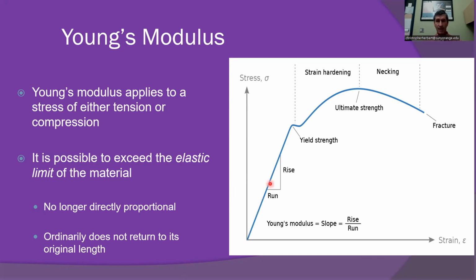But once we go past some point, in this case, we're seeing something called the yield strength. We go past, the material begins to deform permanently, and eventually, at some maximum stress, the material will stretch out at a constant rate. The stress is actually reduced. So this is really the ultimate strength.